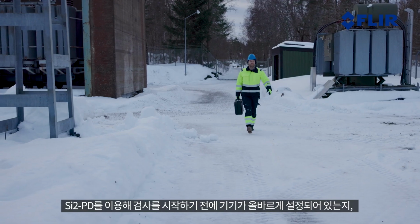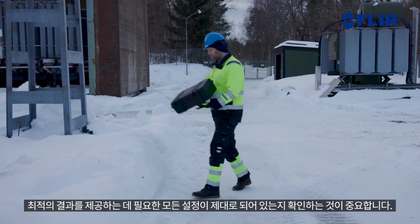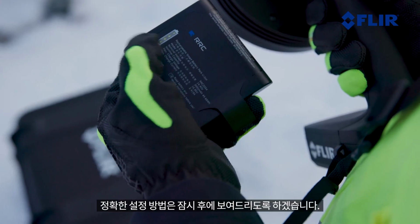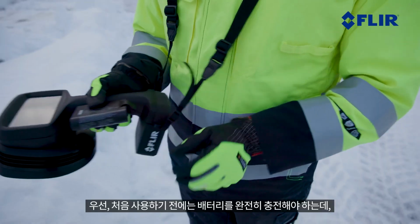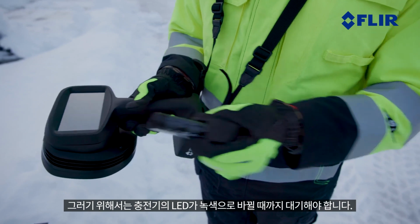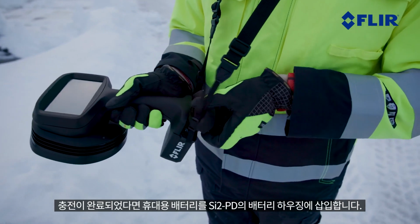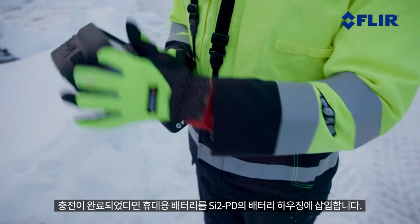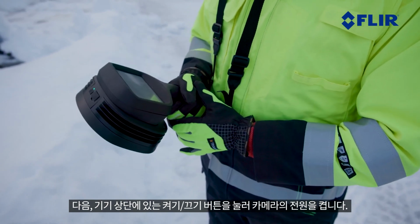Before starting an inspection, make sure your device is set into the correct mode and that all the necessary settings are in place to give you the optimal results. We will show you how to do this later on in this video. Charge the battery fully before its first use. Plug the battery into the charger until the LED on the charger turns green. To start using the Si2 PD, make sure that the portable battery is inserted into the battery housing. Turn on the camera by pressing the on/off button on the top of the device.